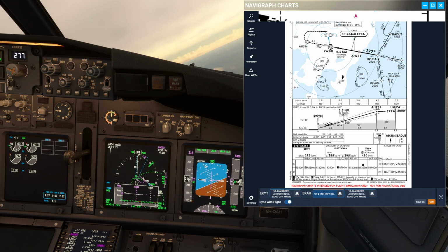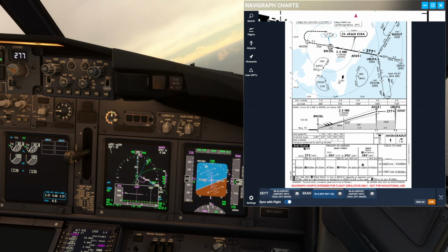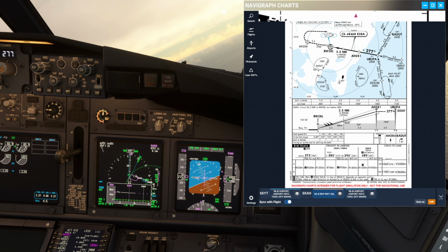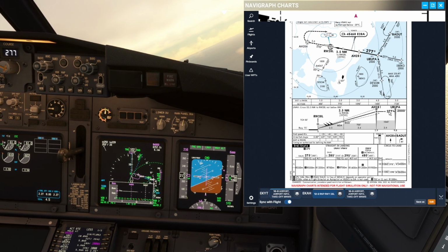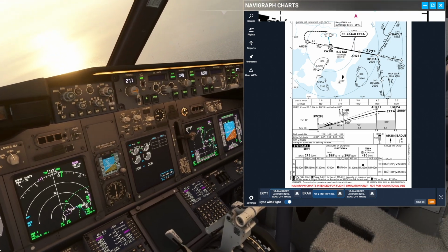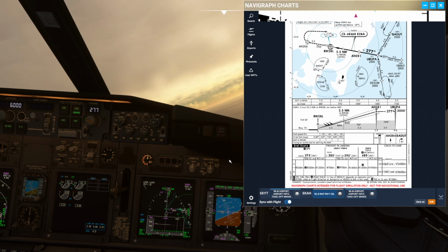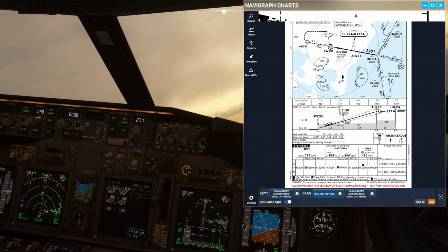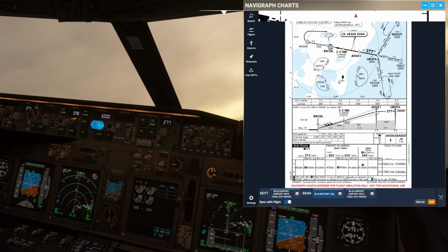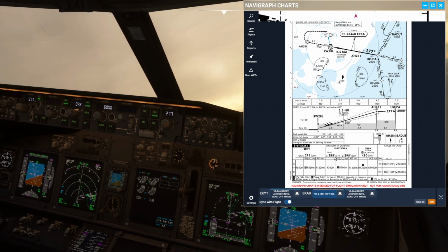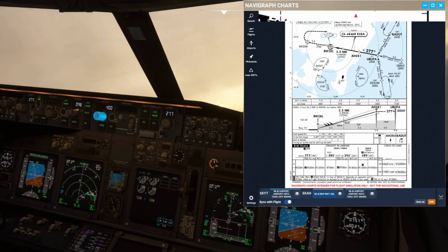What we want to do is, we want to at some point make sure the aircraft is going to descend us all the way down to our minimums. The way we are going to do that is 2 miles prior to our final approach fix, I want to have my pilot monitoring call me approaching descent. When he calls approaching descent, which is 2 miles prior to the Alpha Hotel 281 point, I will set the revised MDA, which is going to be 400 feet. So I'll set 400 feet in the MCP. I'll verify LNAV, VNAV path, and speed intervene, okay?